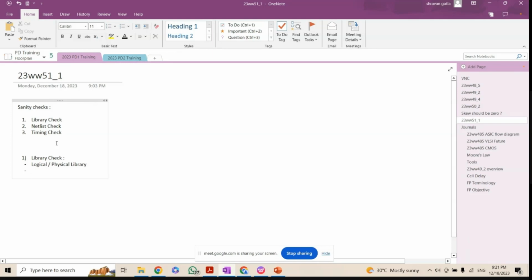To avoid this kind of confusion, they will give the input and output delays on each port. Input and output delays will be defined in the SDC. I think we already learned in the SDC inputs, there is a point in IO, input and output delays it contains. We learned it actually. That information should be given in the SDC. So in the SDC check, the sanity SDC check also checks whether all IO delays are properly defined or not. If not, your timing won't be met.